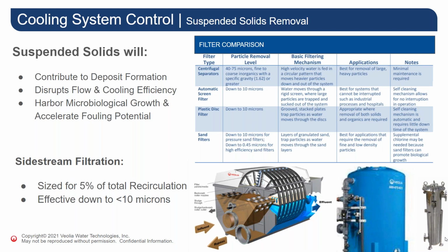And in addition, scaling can be reduced with side stream filtration by limiting fouling and corrosion byproducts, which can also contribute to scale formation on the heat exchange surfaces. Effectively managing these conditions through filtration can optimize system performance, often resulting in moderate to significant energy and water savings.